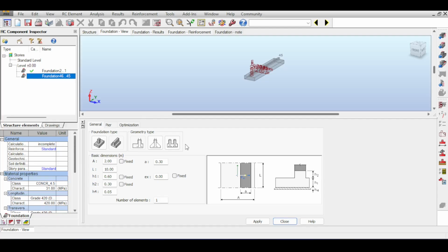Now, of course, you need to try this yourself. For example, H1, which is the height of your foundation, is going to be 0.3 because 0.1h. And by the way, it's going to be 0.35 because your h is 3.5: 3 meters height of soil and 0.5 depth of foundation. So I'll fix that, and you can see where this is going. So I will quickly video edit this again.